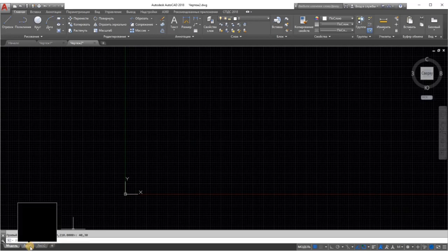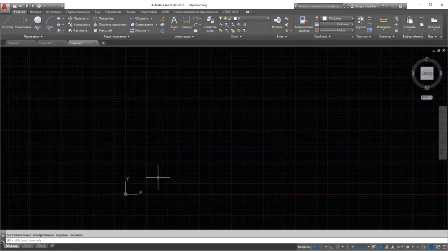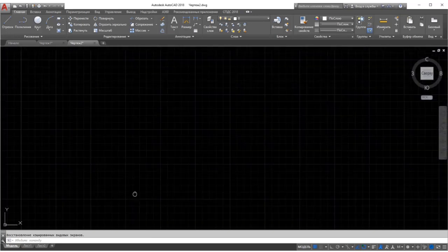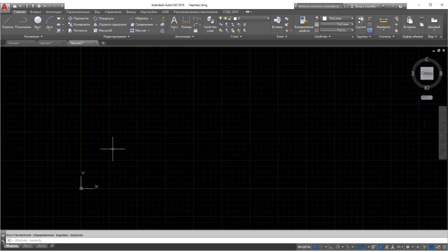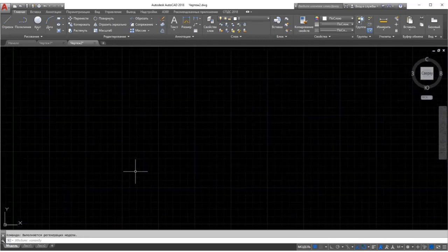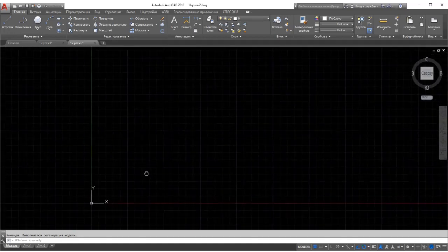To check the area size for yourself, move the crosshair cursor to the upper right corner of the drawing area and observe the value in the coordinate readout in the lower left corner. The coordinate readout won't show exactly 12 by 9 inches or 40 by 30 centimeters for metric, because the proportions of your drawing area aren't likely to be exactly 12 by 9 or 40 by 30. AutoCAD does try to optimize the display for the drawing area when you choose the All option of the Zoom command.